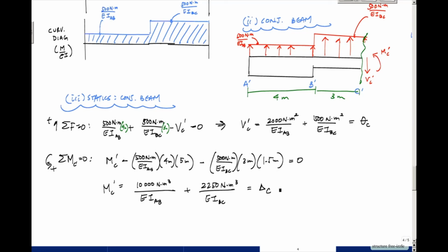Bam. And what this means, if we want to interpret some stuff, there are things you want to check all the time, or units, right? And so here, I noticed that I made that mistake earlier, but the units of EI are Newton per millimeter squared times millimeters to the 4th, which gives me Newton millimeter squared. And I can convert this to meters, obviously, but it's just force times length squared, and the units are going to cancel out, and that leaves theta dimensionless or in units of radians, okay? So typically this answer is in radians,